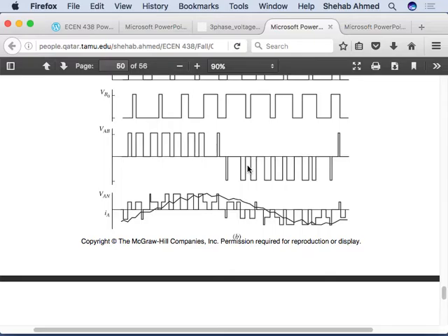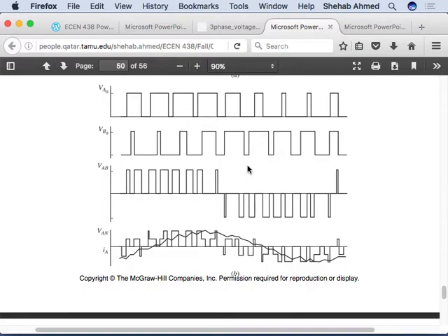I mean, people would like to use it, but you will be limited in how many pulses you can add per cycle by the switch that you choose, and the switch that you choose will depend on the rating of the equipment that you have. So if you end up with a very slow switch, 2-3 pulses per cycle, then you really have to calculate the Fourier series, because then the power quality will be an issue, and then you will have low order harmonics that are an issue. But if you're able to switch high enough and get many pulses per cycle, then you don't have to worry.